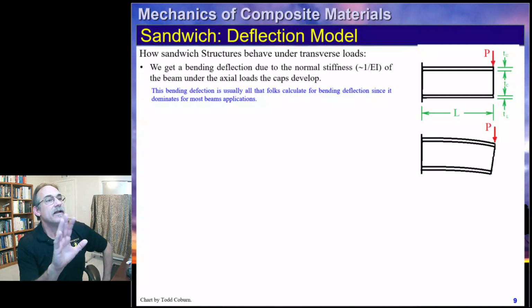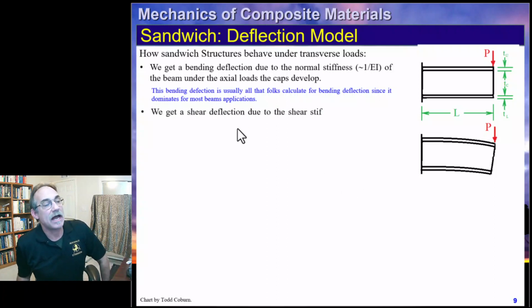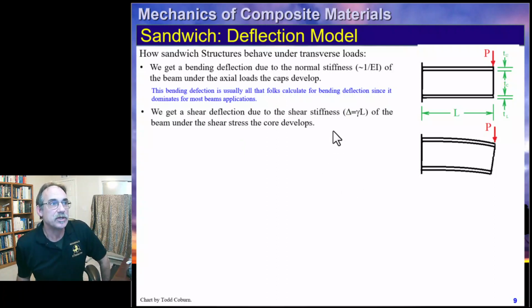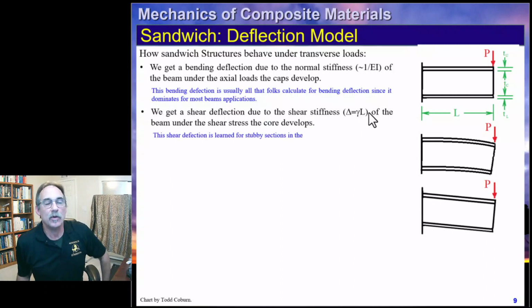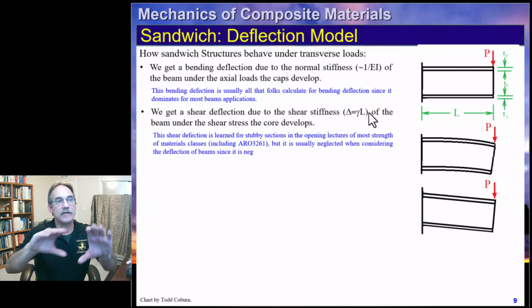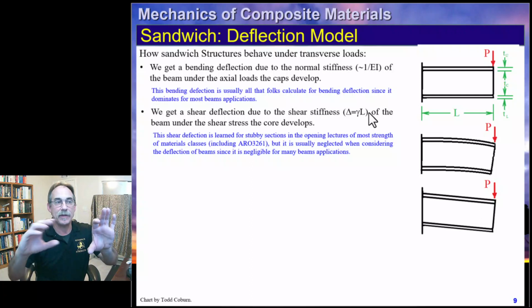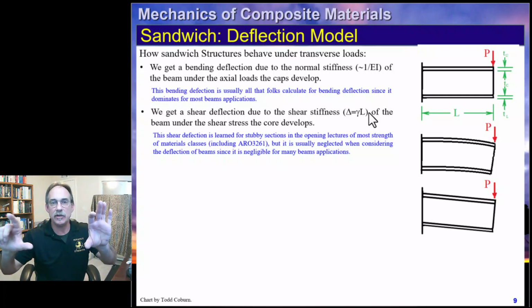So we've got the bending deflection, that's what we're talking about here. We've also got our shear deflection, which we're going to look at. Remember, shear deflection is just gamma L. When you look at that whole thing ratcheting as a unit, you'll notice the first one, where the axial properties were used to evaluate the resistance to bending, we get a nice continuous change as we get more and more deflection.